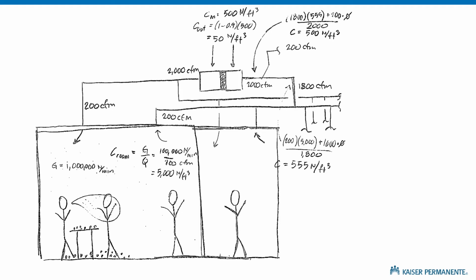You can also set up this whole scenario with conservation of mass by keeping the room concentration and the supply air concentration as 2 unknowns. Then you just write 2 equations and solve for the whole thing that way. Doesn't matter, the answer is going to be the same.